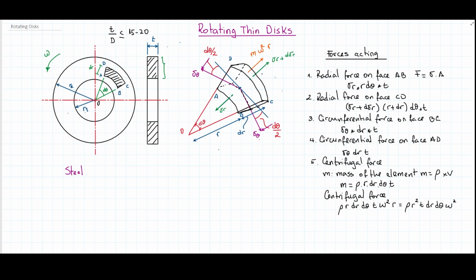There it is. Perfect. But then similarly, what's going to be the area where this stress is applied? It's going to be this circular segment times the thickness. And the circular segment is, well, how much is this angle here? That angle is the same delta theta. But then the radius is going to be what? The radius is going to be r plus the whole height of this segment, and that's why we have the stress times the radius times the angle times the thickness of the surface. So that's going to give us the force on this surface here.